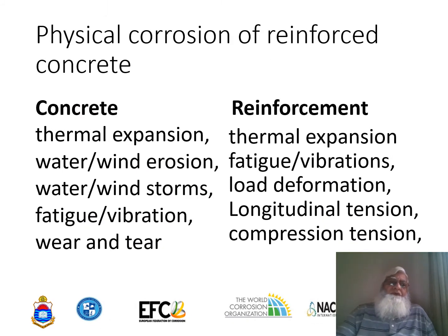Physical corrosion of reinforced concrete. Concrete thermal expansion, water, wind erosion, wind storms, all these things are causing the actual deterioration of the concrete. The thermal expansion comes mainly from the high temperature, which can expand the iron in there, and the concrete, due to the low temperature and high temperature cycles, and the water from the channels or the wind erosion.